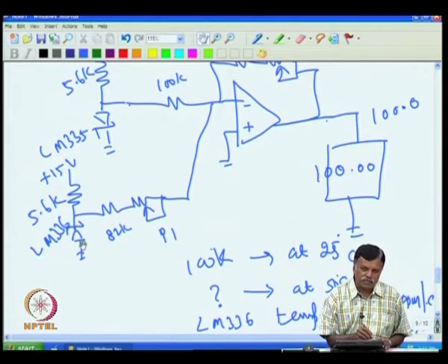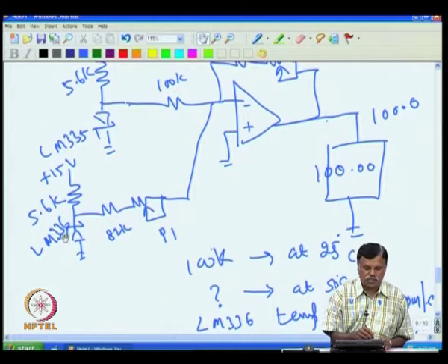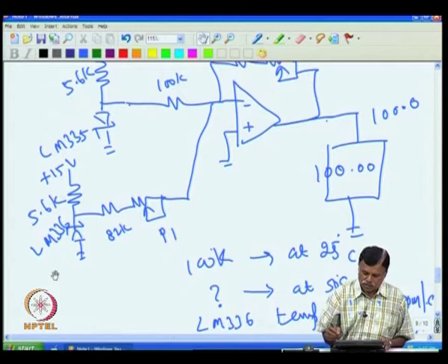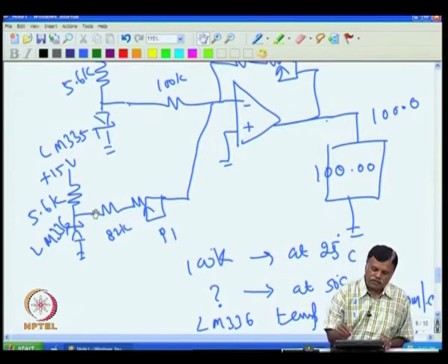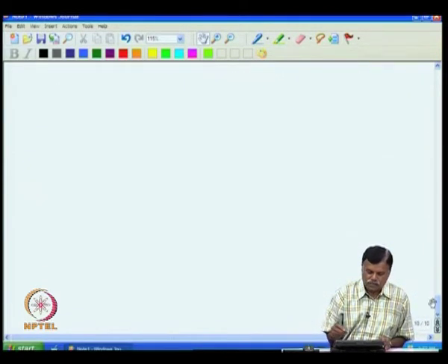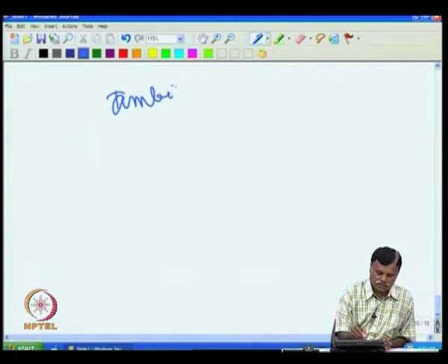I am not talking about temperature measurement, I am talking of the temperature the instrument is used in. So, we know that this changes by 30 ppm maximum, that means for 100 degree, a 3000 ppm change in voltage is possible for the worst case temperature change. So, what will be the voltage change that is expected at the output? Considering the industrial grade equipment, I take it as 100 degree ambient temperature change. This is for industrial grade equipment.